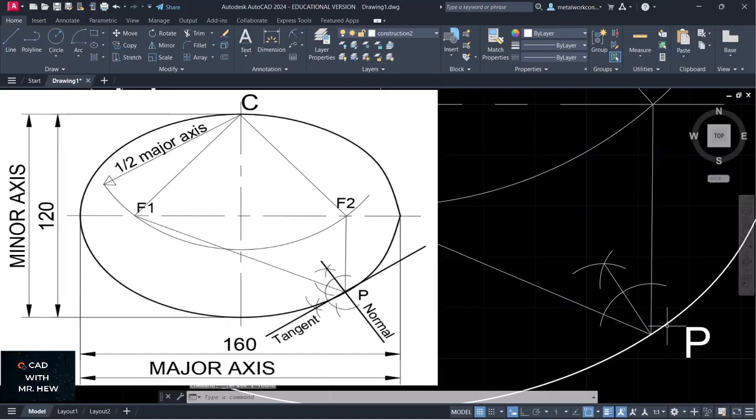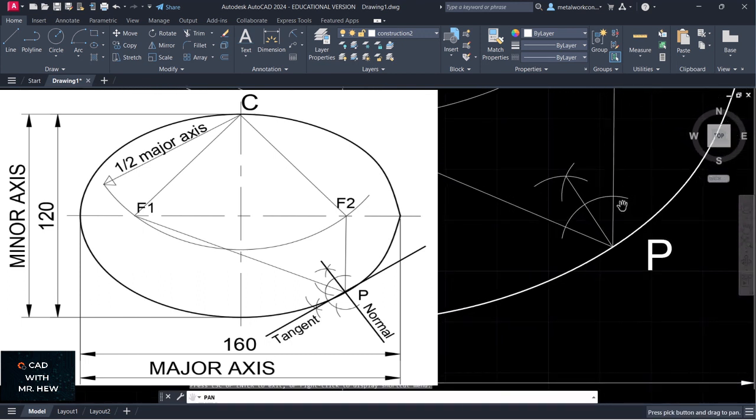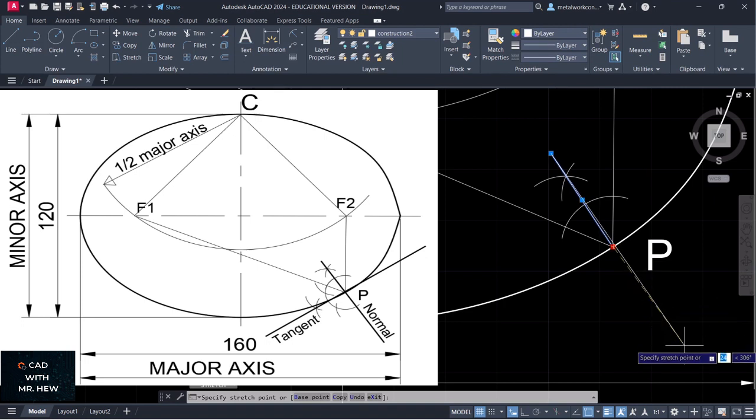All right. So what I'm going to do is extend this line a little bit beyond the bisector, about there. I'm going to come here and do the same thing this way. We need to make sure the line is straight. The next thing we're going to do is draw a semicircle on this side because the letter P is over there. I'm going to draw it on this side, but it doesn't matter.